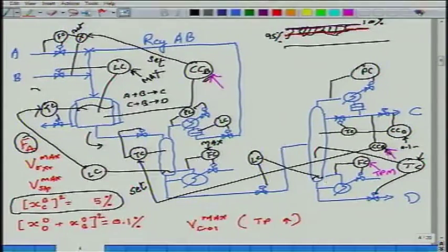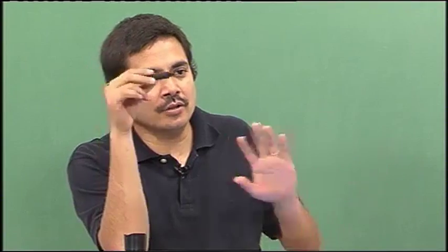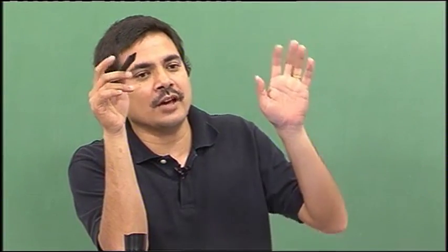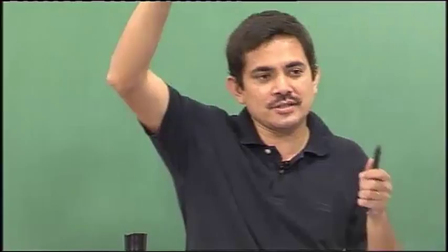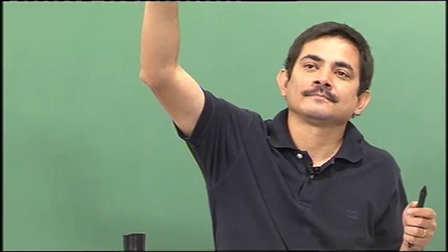Composition of B in the reactor and the impurity B leaking down the bottoms. Once he sets that at some value less than 0.1, the amount of D that is allowed to leak up the top is 0.1 minus that, right. The 2 independent things, degrees of freedom, is fundamental. There is a total of 7 steady state degrees of freedom, 5 active constraints. That means the operator is not free to adjust them; 5 set points will get adjusted to drive those constraints, right. What remains is in the hands of the operator.